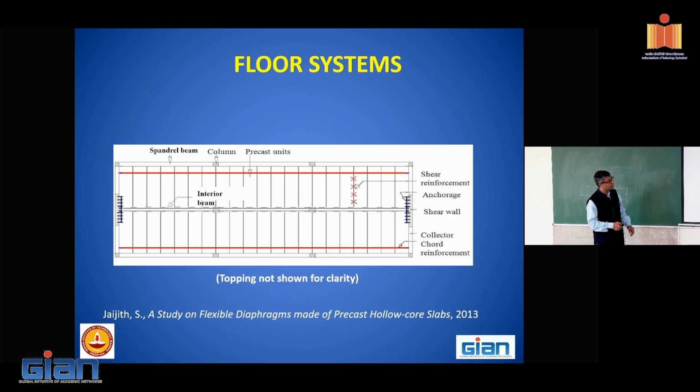Whereas elsewhere, within the precast planks a groove is provided where you put reinforcement and then you just put some topping and flush it. Now, these individual members can be stitched, which is done abroad, by welding the steel embeds that are there in the planks. In our country, we do not stitch them. We provide a conventional structural topping throughout. That gives complete integrity, and we can say that it is like a composite slab.